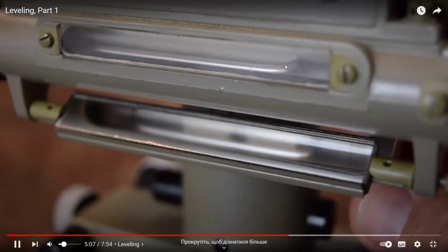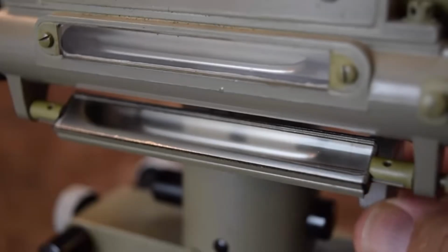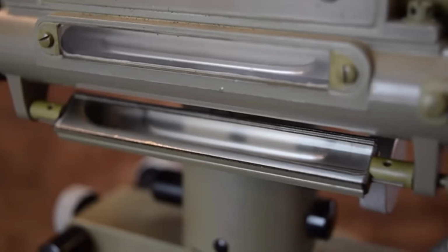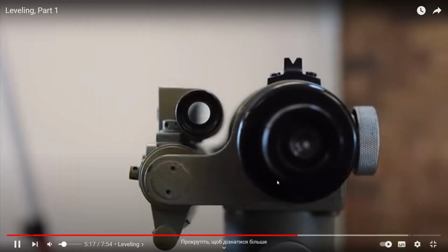Below the long bubble tube, an adjustable mirror reflects light into the fluid and bubble in the cylindrical tube. Using a separate eyepiece and another internal mirror, the operator views two halves of the bubble image and adjusts the level carefully to align the two images. Here you can see the tilting level.